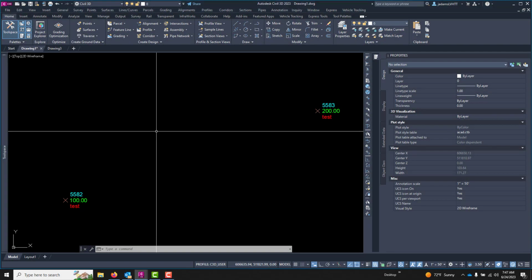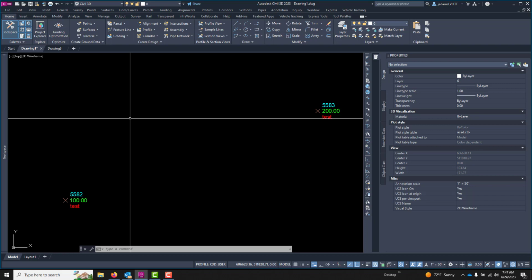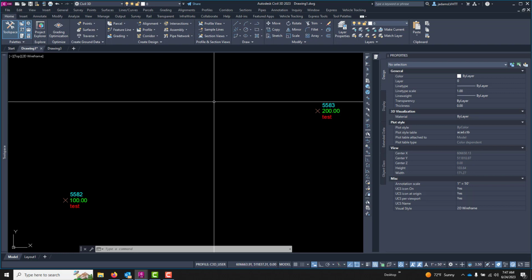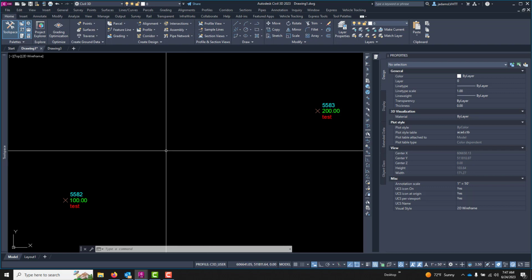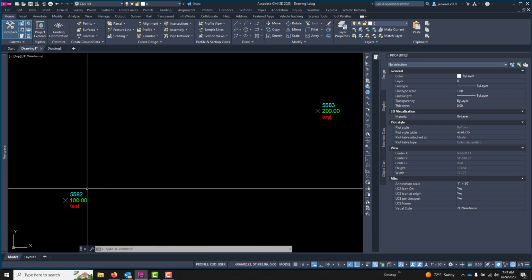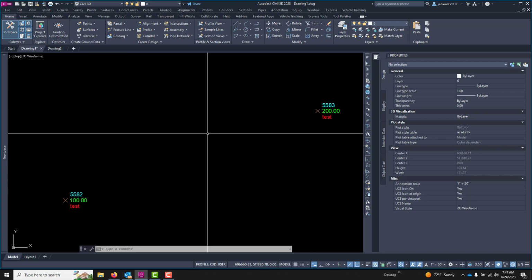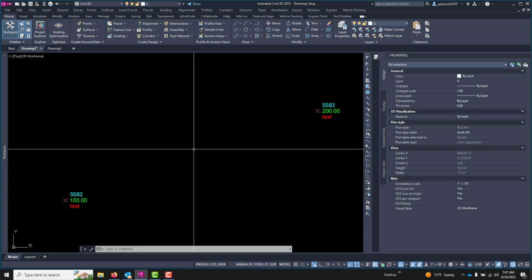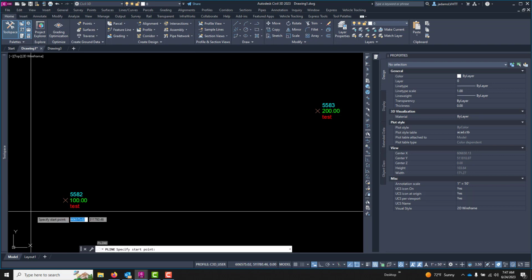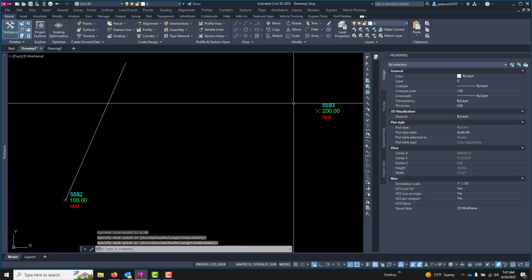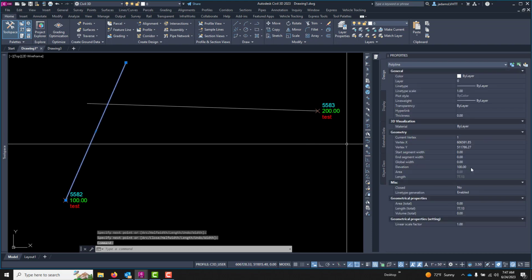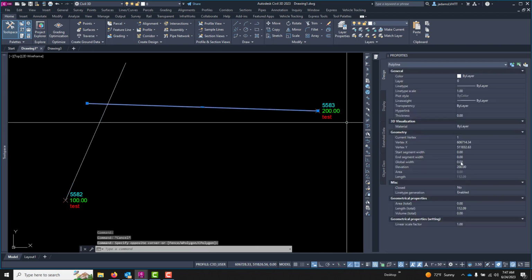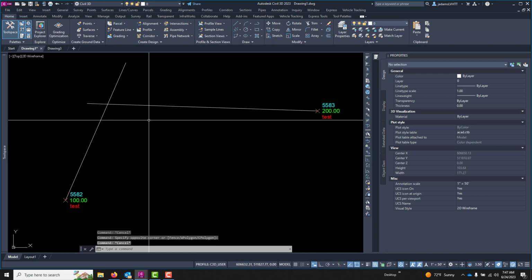Three more quick tips in Civil 3D to help with your productivity and a little bit with your quality of life inside the program. First, let's start with a productivity tip. On my screen I have two COGO points, one at 100 and one at 200. By default, Civil 3D draws objects in 3D. So if I drew a polyline from that node and one from this node, that one is at elevation 100 and this is at elevation 200.